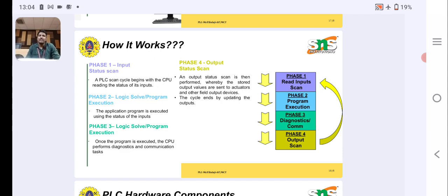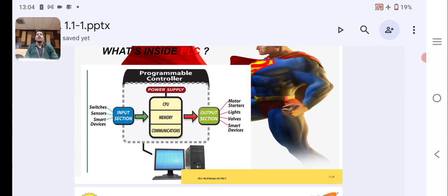The communication interface is used to receive and transmit data on communication networks, in the CPU and to other PLCs. It is concerned with such actions as device verification, data acquisition, synchronization between user applications, and connection management. Here you can see PLC1, PLC2, the supervisory systems, machine and plant 2, and the communication networks. Most people use Modbus and Fieldbus for process conditions.